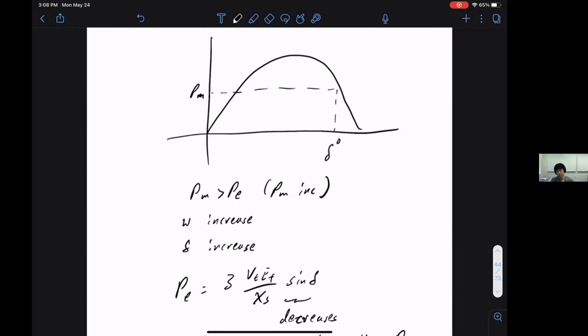Got it. That makes sense. Thank you. Right, so that safety margin is to ensure that when you have a disturbance, you don't even come close to 90 degrees. In the system, most likely we're pretty much limited by this angle. A lot of times when we cannot transfer a large amount of power from one part to another, it is not because we can't generate the power, and not because it will melt the transmission line or produce too much heat. It is because this angle is a problem. We cannot let the angle be too big, because an unstable angle is the worst thing that can happen in the system. You want to control this very tightly.